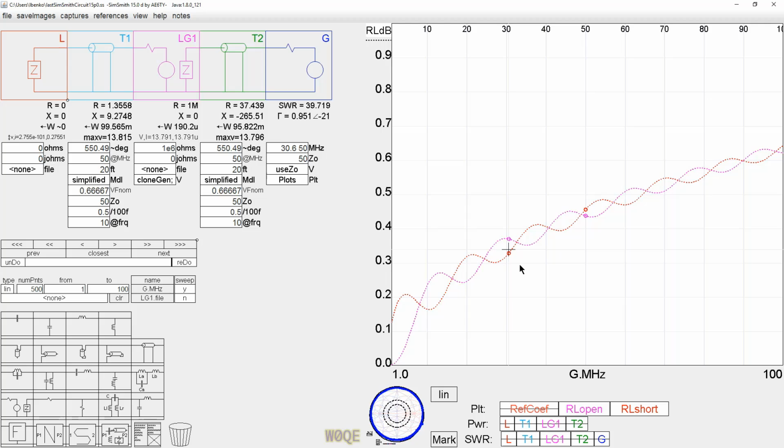And based on the frequency you've got, and the kind of length you have versus the frequency, you end up with a different number of lower loss sections and a different number of higher loss sections. And those lower loss and higher loss sections contribute in such a way that as you change the frequency, the loss actually can go down a little bit, which is really, really interesting. It was something I was really surprised by. I think the first time I saw it was probably about 20 years ago, and I was absolutely amazed.